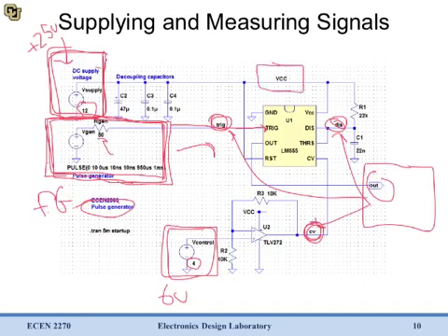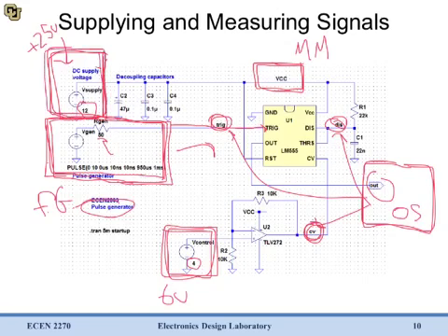If we wanted to double check that our voltage rail was at the correct voltage and that it was clean, didn't have a lot of noise on it, we'd use a multimeter for that. So we're using our oscilloscope to measure outputs because we expect them to vary. We're using our multimeter to measure voltage rails because we expect them to be constant. We have our power supply generating both of these sources here, and our function generator set up for our input. So that's the basics of how you use this lab equipment. Most importantly, go into the lab, try and hit some buttons, try and figure out what does what. That's really the best way to learn this equipment.